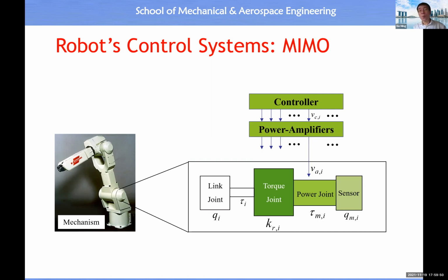So it is very difficult for us to study or play with a MIMO system. You remember there is a property for LTI systems: if we have an LTI system, then MIMO becomes a sum of SISO. Therefore, our target is to see under what condition the MIMO system of a robotic arm could become a sum of SISO systems.